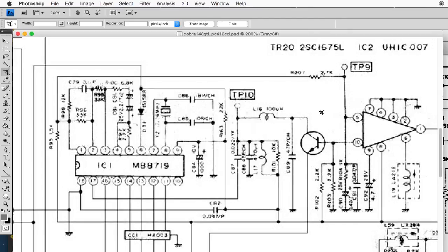So I thought, right, I'll do another video and cover the function of the phase detector and how that outputs, and that loop filtering is quite important, because if you do have issues with any of these capacitors, it may stop your loop from locking, because these are supposed to filter out the high frequency content and smooth it out into a DC supply into here. So you've got these pulses coming in here, those little square wave pulses or sine wave pulses, maybe, usually square wave.